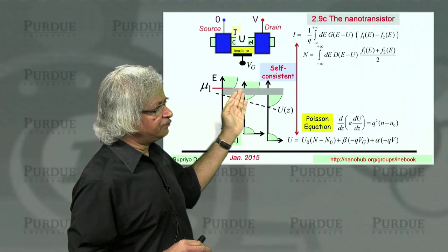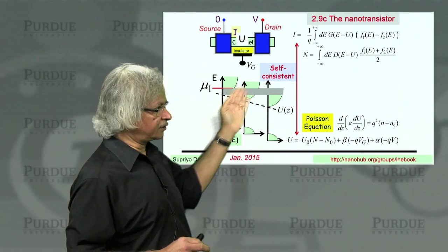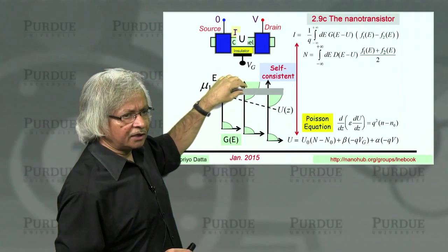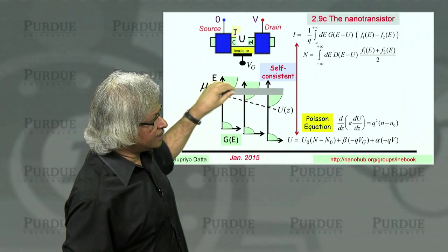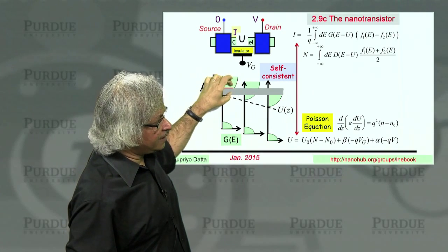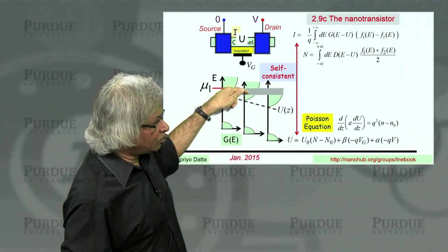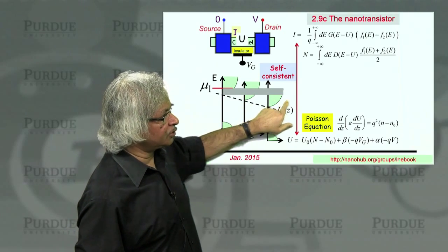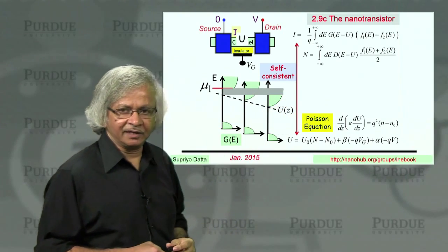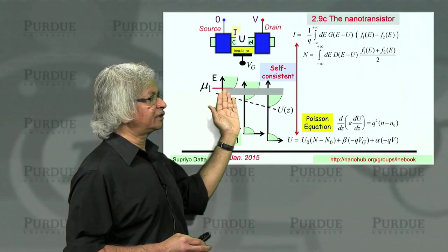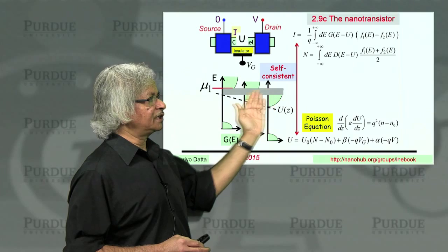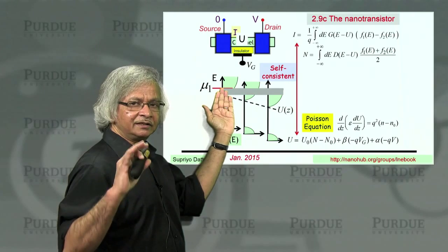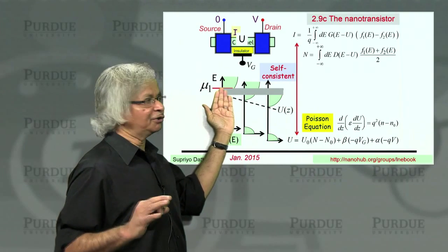But on the other hand, if you have diffusive processes going on, so that electrons lose momentum in here, then there would be a lot of situations where these electrons, instead of being confined to this energy channel, would want to go down here. And once they go down, they are able to carry on to the drain. So the point I'm trying to make is, if you have a model which allows electrons only to travel in the channel they started in energy, then you'll tend to calculate a much lower current than what you actually get.